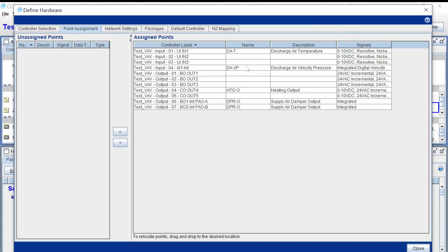And I highly recommend, guys, if you work with the folks that are doing your jobs, or if you are the guy doing those jobs, write that down somewhere. Set up some kind of an Excel spreadsheet. Set up something to where you have those values listed somewhere for future reference. If you have to replace one of these boxes and you want to make sure you get all of those balance values back in there, it will come in very handy to have that data available.